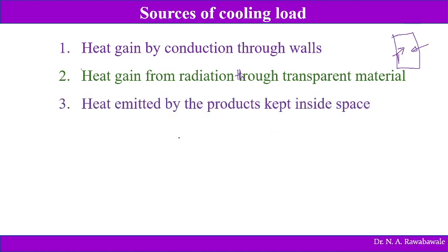The next one is heat emitted by products kept inside the space. Say for example, if you keep germinating seeds inside the refrigerator, germinating seeds always tend to liberate heat energy. That liberated heat energy also adds to the cooling load of the refrigerator. Likewise, if you keep hot milk in the refrigerator, that hot milk emits heat energy into the refrigerator, so that adds to the cooling load.